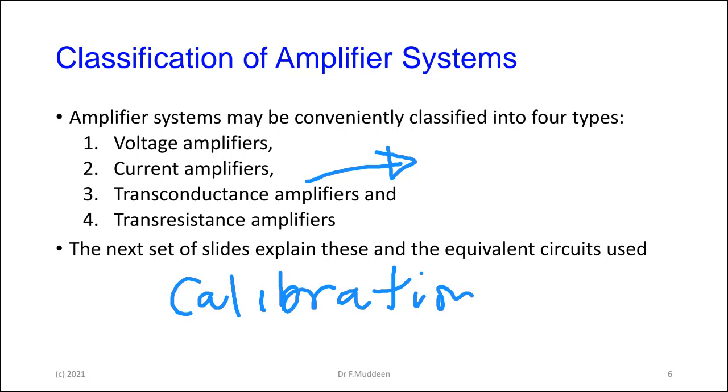What it basically does is that you put a standard voltage in, and it gives you a very, very accurate current that is a multiple of that voltage in, according to the gain of the amplifier. The ones that I am familiar with would take 20 volts in and give you up to 1,000 amps coming out.